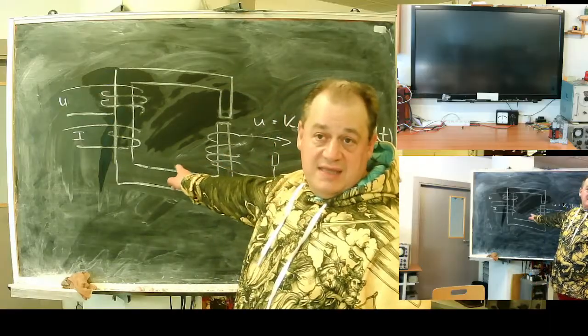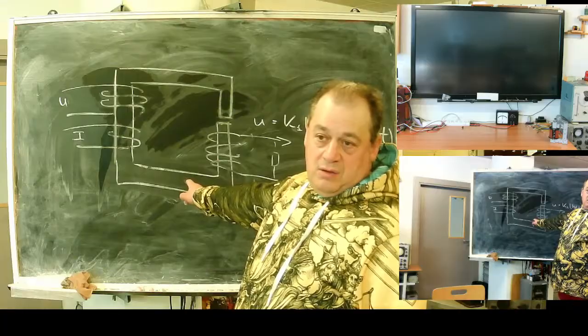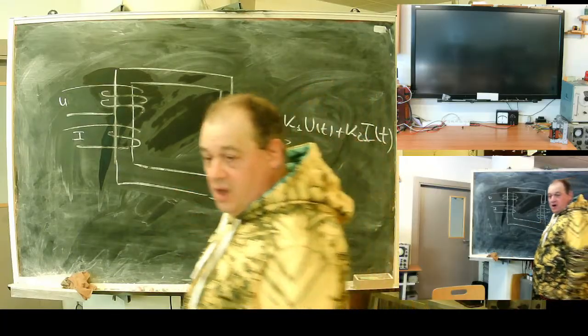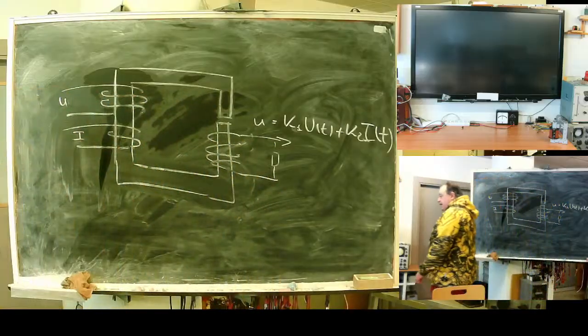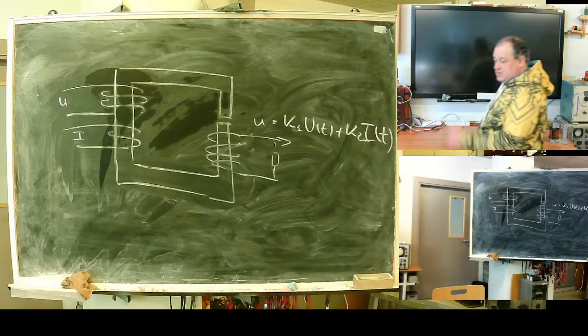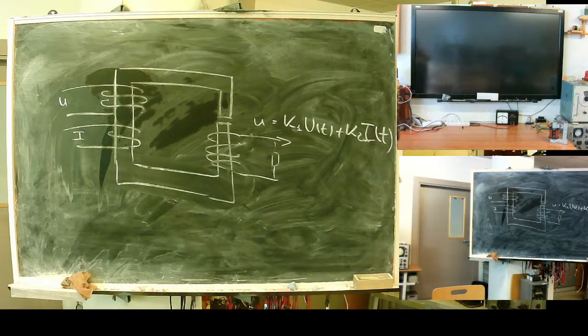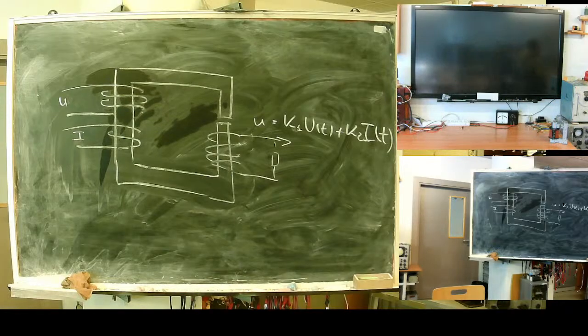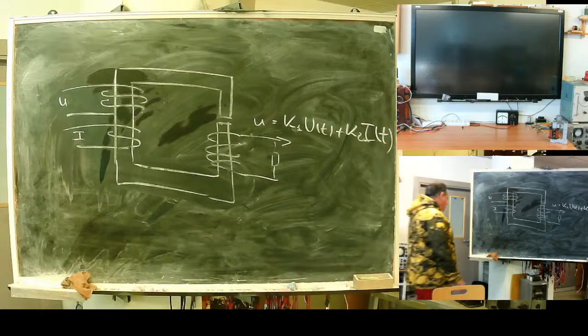Such a thing can easily put a 10 times higher load. I knew cases when the protection system failed when such a device was connected, because of primary current transformer overload. It's not a thing you can ignore. Okay.